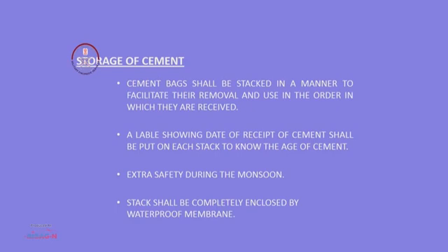Similarly, we have to ensure that it is stacked in a manner so that removal and use are facilitated in the order in which the cement is received. It should be feasible that older cement can be taken out early. It should not happen that we are utilizing the cement which came yesterday while the cement which came 1 week back is still there. We have to ensure that the older cement is taken out first. So stacking and storage should be done in that manner only.